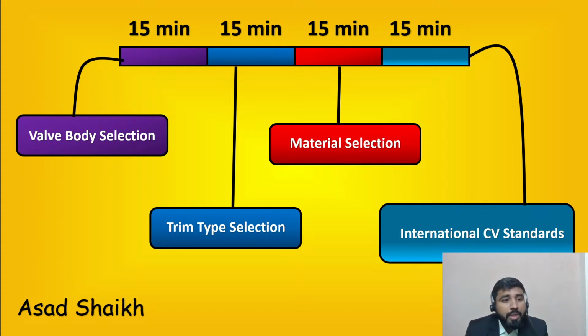Okay, I see a question. Based on process fluid, one class higher than pipe. Based on the liquid in the line, the process medium. One higher than what piping has taken, project piping specs. Based on temperature, based on PMS.